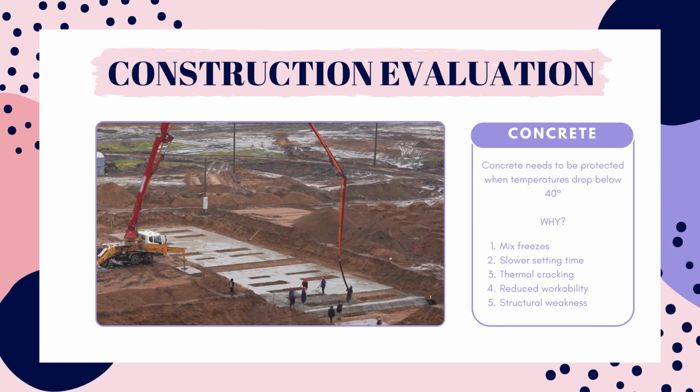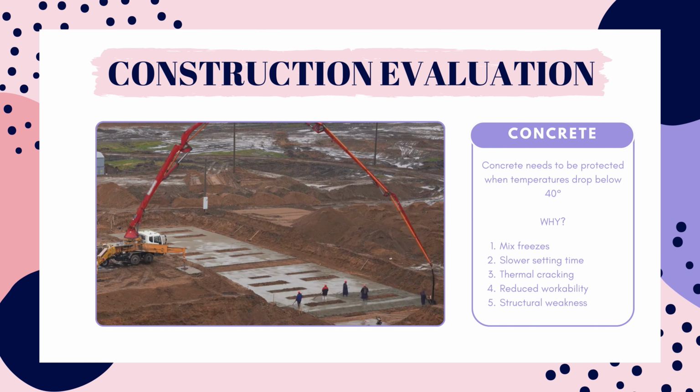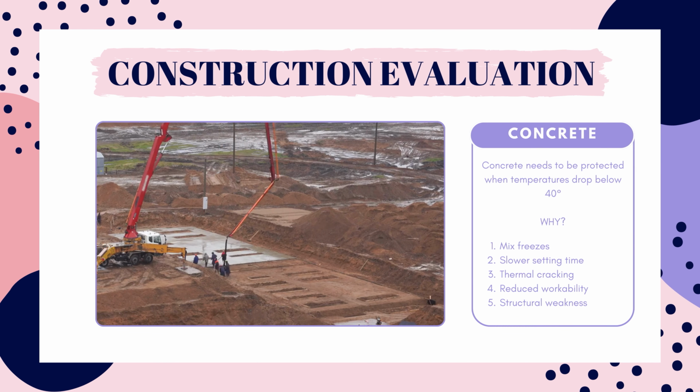Overall, pouring concrete in very cold temperatures can lead to structural weaknesses, surface defects, and other problems that can compromise the integrity and durability of the concrete. It's generally recommended to take precautions such as using insulating blankets, heaters, or additives to maintain adequate temperatures during cold weather concreting.